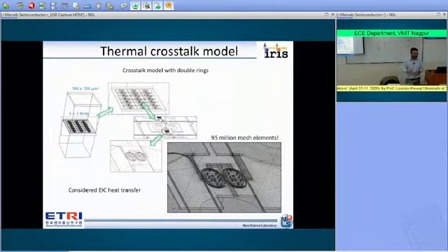If it is, it means that we want to switch one node of the matrix, and indeed we are switching all the nodes around it. This effect is called thermal crosstalk, meaning that we want to hit this node and we are also hitting the other nodes around. And this we want to avoid.